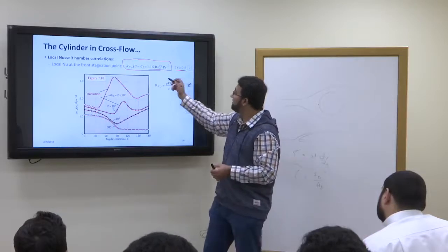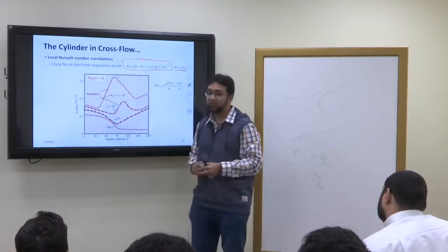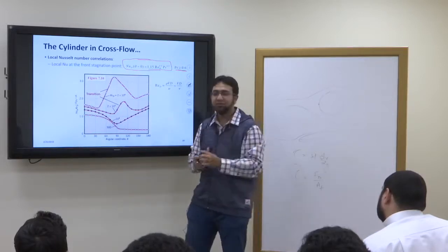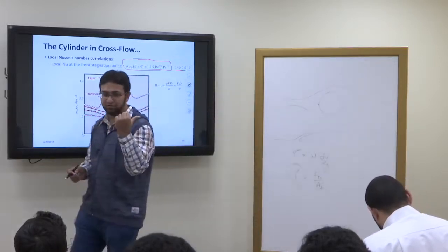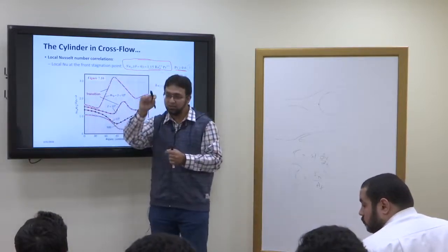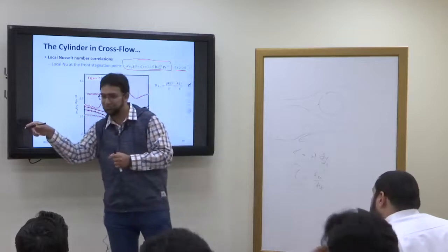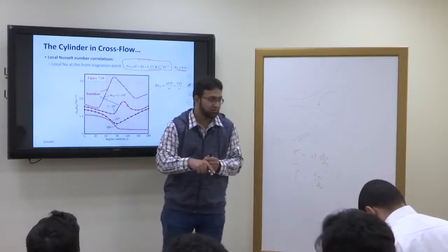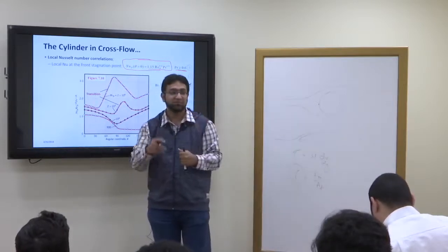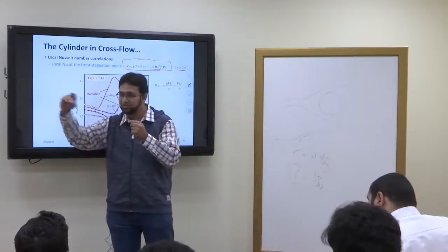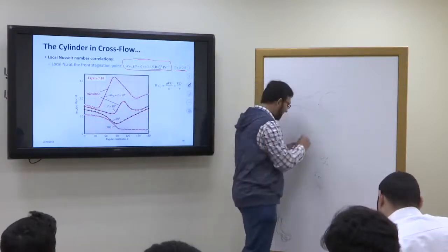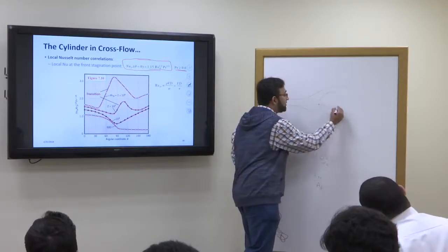So this is the Nusselt number for theta equals 0. This is the local Nusselt number, right? Remember, when we were studying the flow across a flat plate, we studied the local Nusselt number and the average Nusselt number. In the previous case, the Nusselt number was varying with the length, with the distance. Now here it will not vary with the distance, rather it will vary with theta.